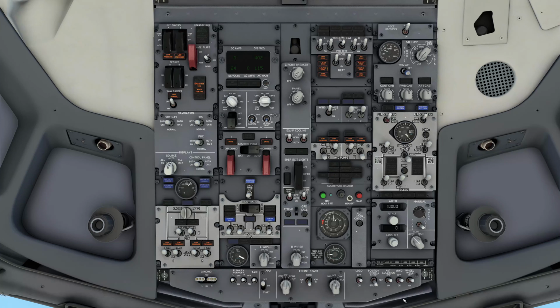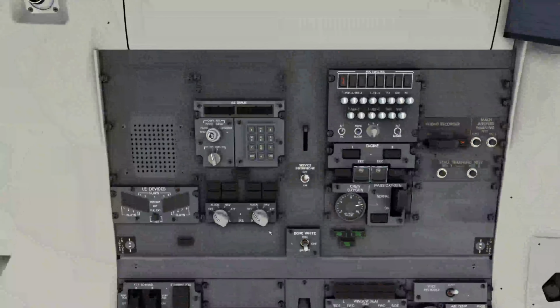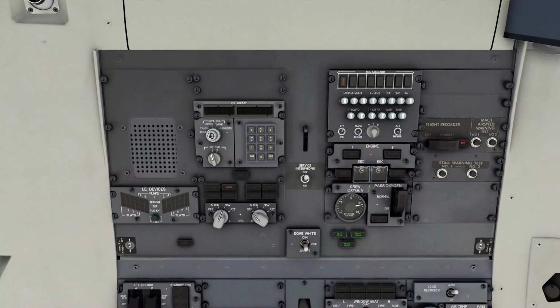Now, lights as required. We are on the stand here. There's power to the aircraft, so we're going to turn the position lights down to steady. And then we are going to start the IRSs aligning. So we'll go up one more panel, and we're going to turn the two IRSs over to nav.